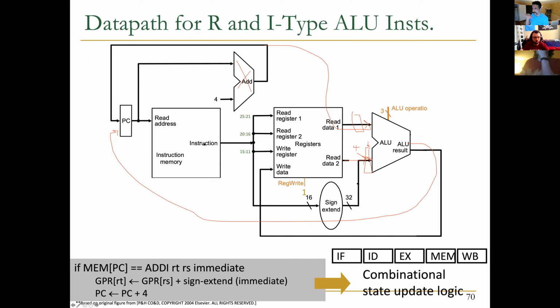Then instead of reading the current instruction, we will read the next instruction, which is obviously not what we want to do. So this write signal here, and also this part, need to be coordinated in the right way in order to execute things semantically correctly. So adding this extra overhead of coordinating, and since we have one resource at a time, this ALU cannot do both things at the same time. So there would be a need for coordinating these things, and it adds some overhead. So obviously we could, but again, performance trade-off, right?